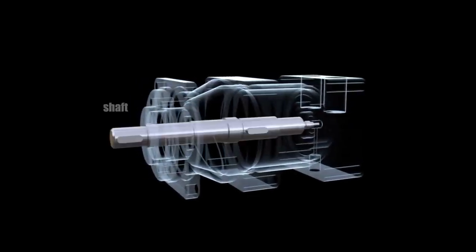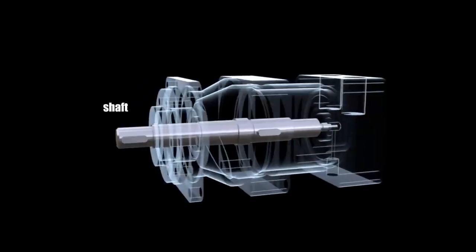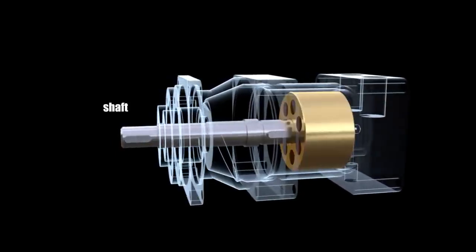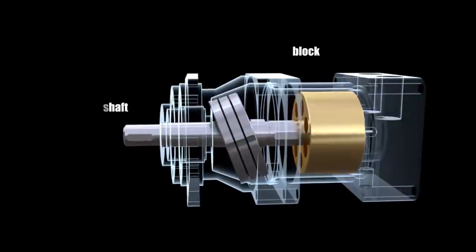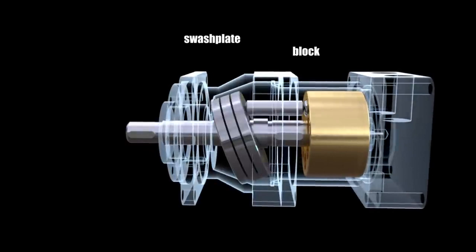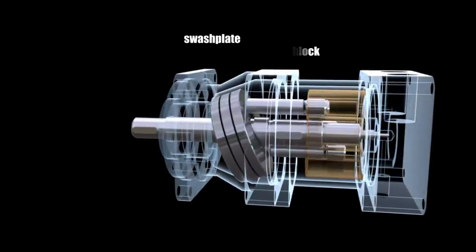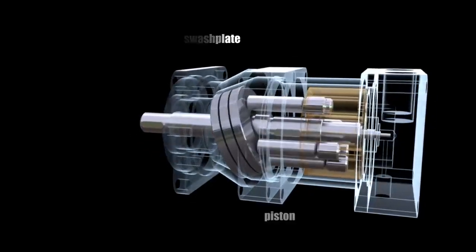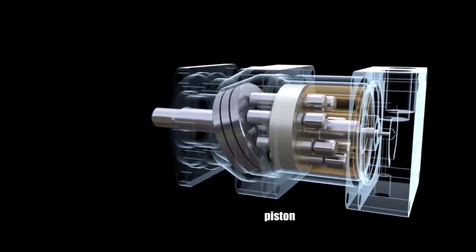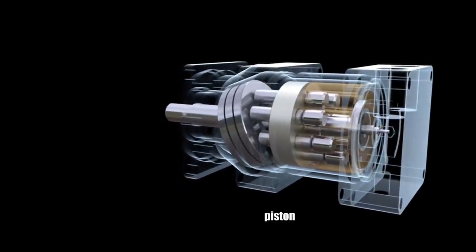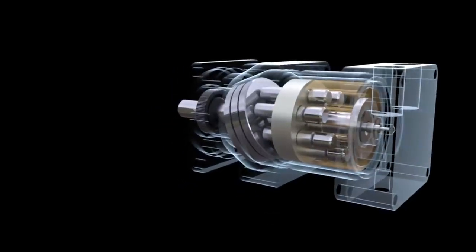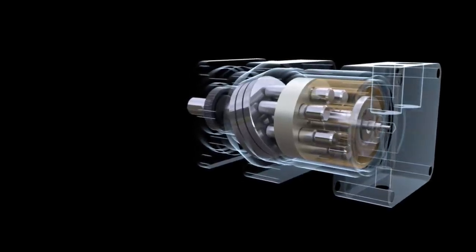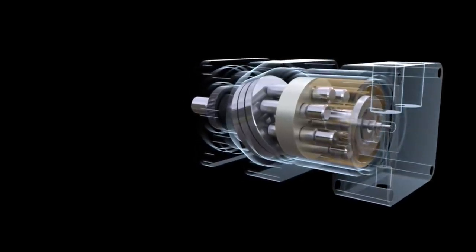The cylinder block of swash plate pumps is installed coaxially with the drive shaft, and the rotation is usually transmitted to the block using a key or spline connection. The pistons rest on a swash plate supported by special pushers that have a spherical surface. The cylinder block is installed on a valve plate connected to a rear cover, in which there are channels for connection with pressure and suction pipelines.